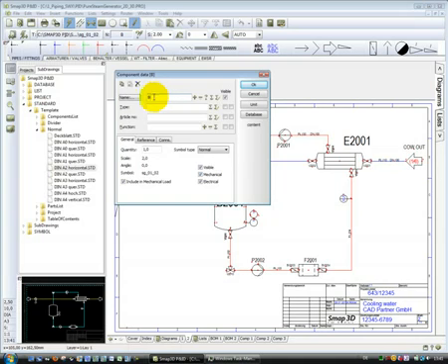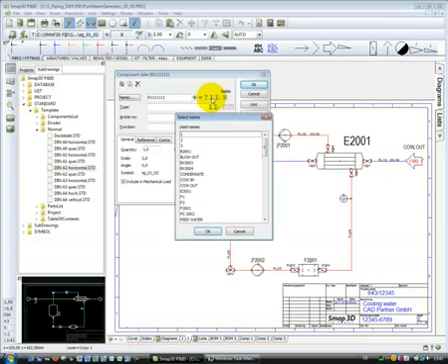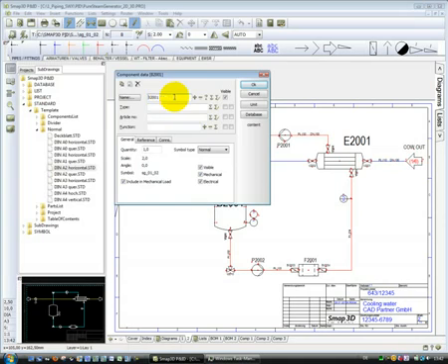This tag number can be created by typing in some value or by selecting some used and prepared values. For example, if there is an existing numbering syntax prepared somewhere, a user can select it, for example here with 1 letter and 2 numbers, select it from this list and use a function called nextFree to count up to the next free number which is not used in the system. If this is specified, we have done the required work for placing new symbols.